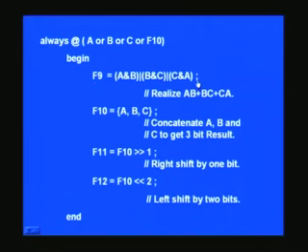If you forget this, the compiler will promptly report an error, and we will be learning all those gradually. The next example was concatenation, as we have already seen, and it is precisely what we have seen pictorially. These flower brackets concatenate the ABC signals. Suppose you want C as MSB, you should put C here and then A comma B, in any order.